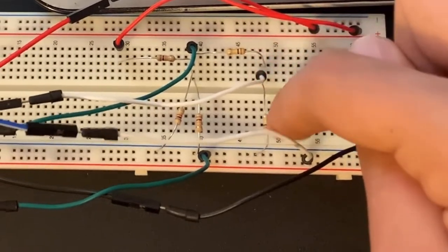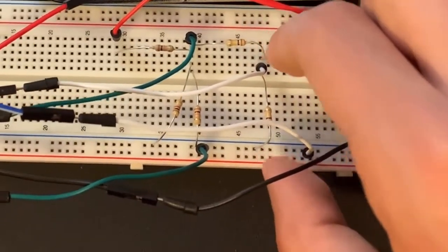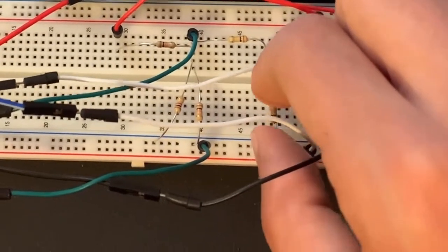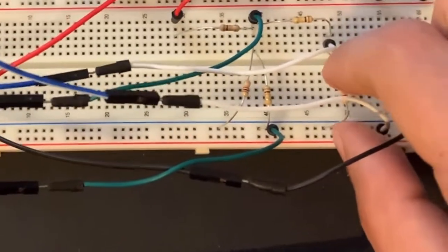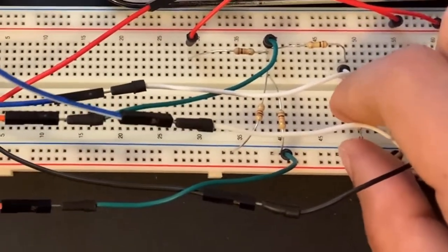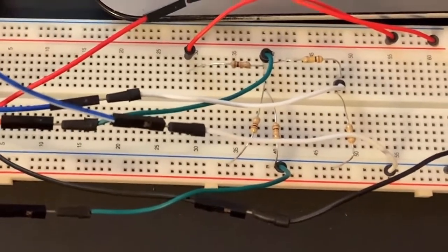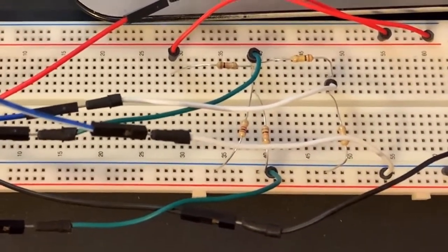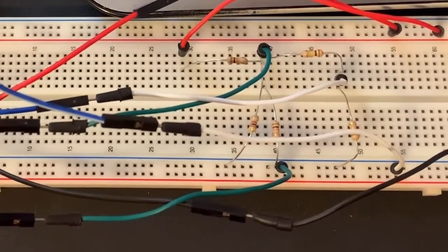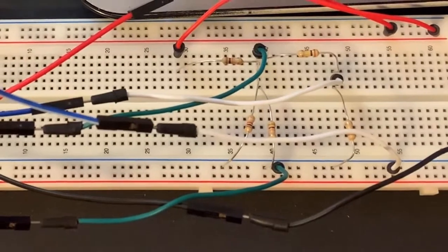So the voltage is equal to V2, the drop over R5, divided by the value of the resistance R5, which is equal to 100K. So you get 0.00191 milliamperes. So this is it for part 2. And if you compare the theoretical values with the measured values, you'll find that they are very close to each other. So this means that your circuit is connected in the correct way.